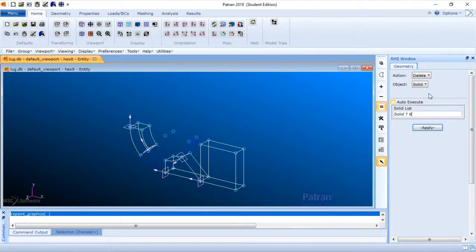So now we're gonna delete plane, and since we created 5 planes, we're gonna delete all of them. We're gonna write here plane 1 to 5. You can also select them manually, however you prefer, but so it can become faster, I prefer this method. Refresh, and as you can see, we just have the bottom half, and we don't have any more planes. Also, we're gonna decrease the size of the points, so we have a cleaner view of our figure.